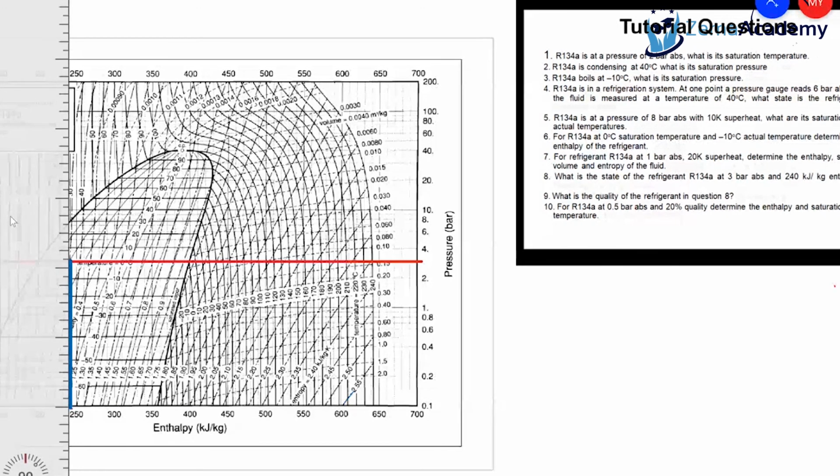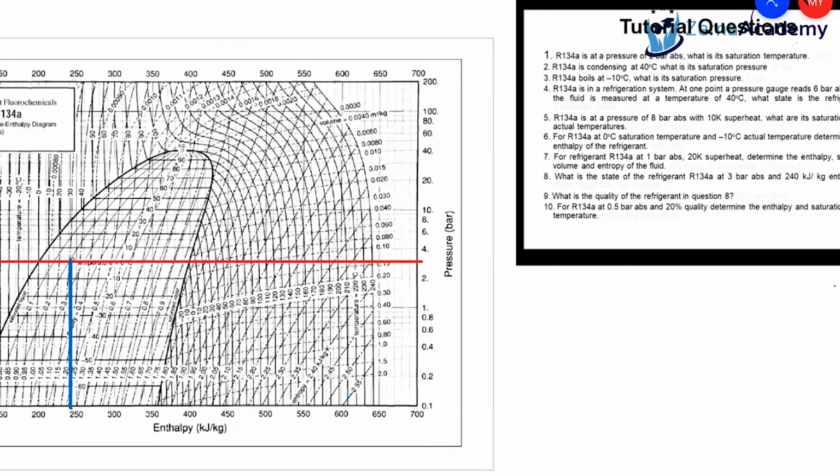Yes, definitely. So this point is the one that we're looking at. The question says, what is the state of the refrigerant? We are around 80% liquid with very, very small droplets of vapor. Mostly liquid with very few bubbles of refrigerant gas. Okay, and that's the question answered. What do you have? Mostly liquid with very little vapor.